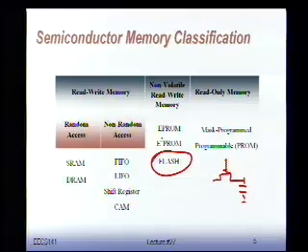But there are other ways of doing non-volatile techniques. You might have heard about FRAM. FRAM is ferroelectric. You use ferroelectric materials, and what you change is not the transistor, but the resistor. Can I program a resistor to be large or small? And if you can sense the value of the resistor, I know if it's a 1 or a 0. Or you have MRAM, where you use magnetic properties to program a cell and change it indefinitely.